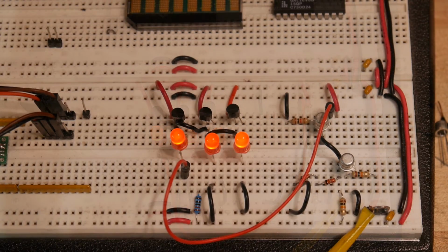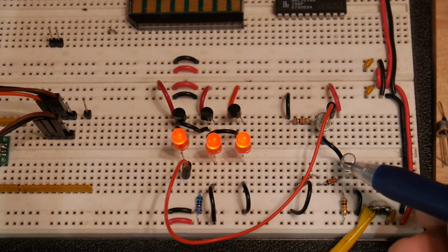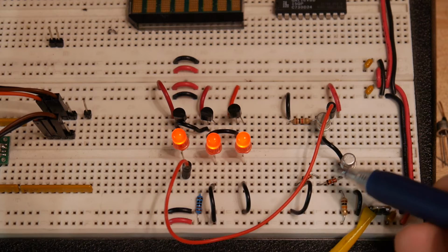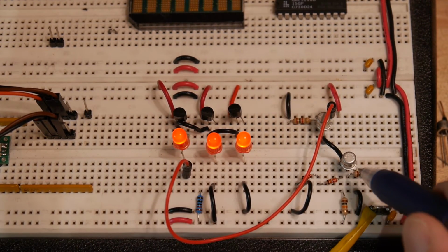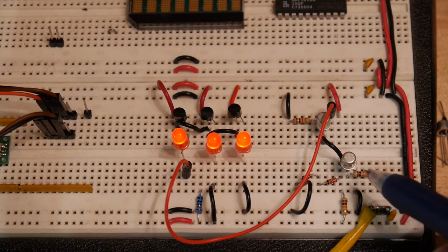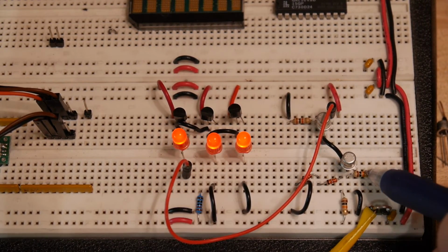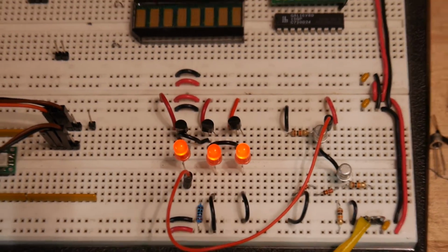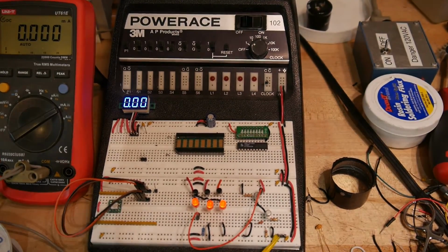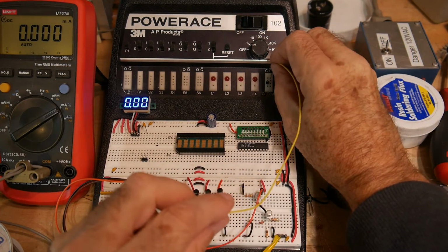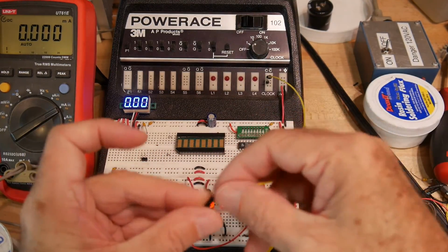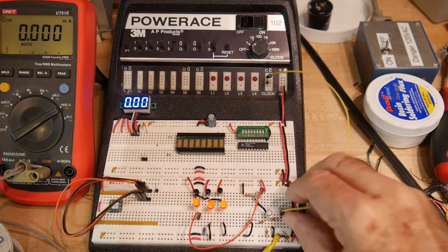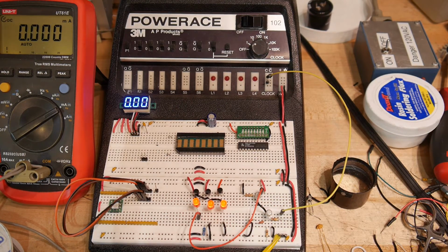All right, so I've added one more transistor. The collector of that transistor is here at the second diode. The emitter is grounded, and then the base has a 10K resistor. And we'll take that 10K resistor and go up here to our clock circuit. Remember, this clock has a 555. This thing has a 555 in it, and there we go.